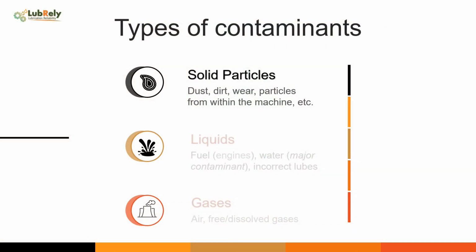Not every contaminant is going to be as damaging as another one, since the material of the contaminant is very important. Less harmful, but still particles, are fibers from cleaning rags, rubber debris from seals and hoses, etc. Also important are of course the physical size, shape, form and the number of those solid particles. The larger they are, the more damage they can do.